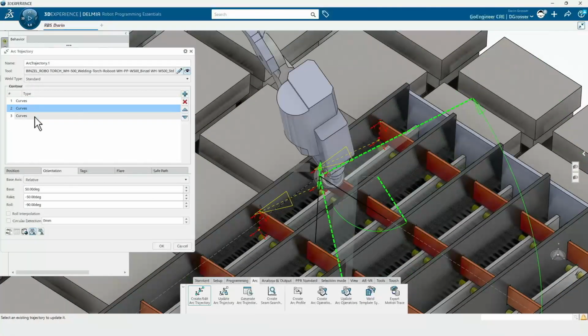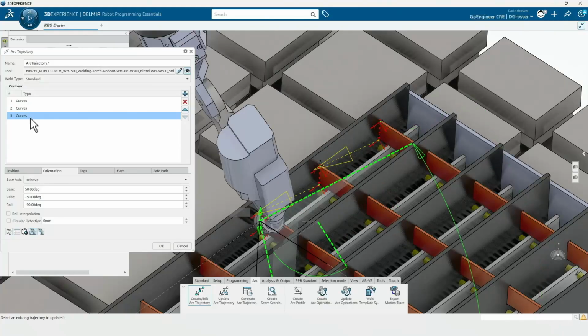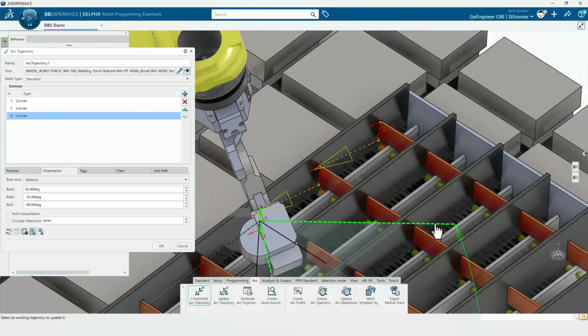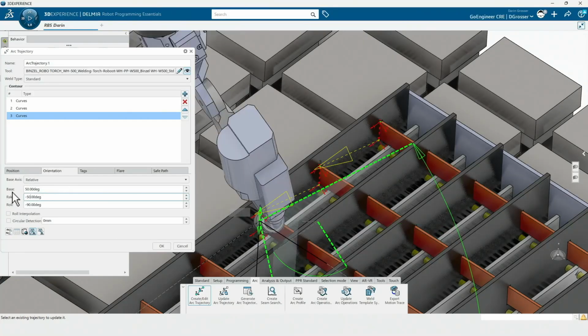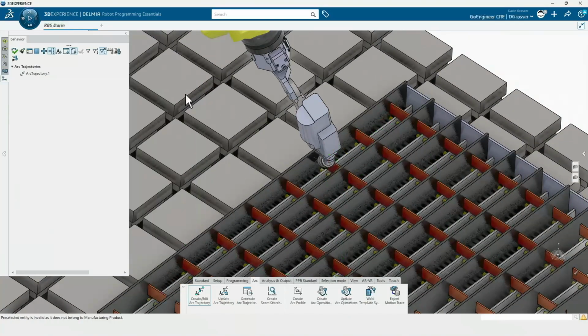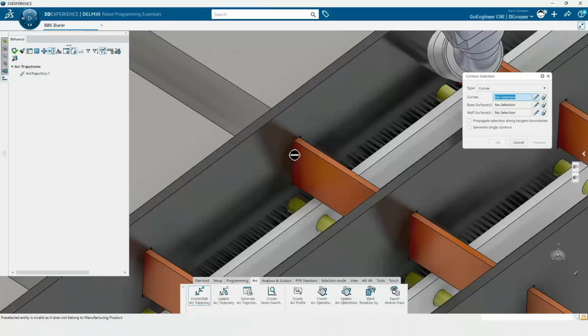Now, teaching also can include pulling that robot out to a specific spot in any way that you want, and then defining that as a point. And what that's going to do is put that into the overall tool path as it processes. And sometimes those are pull away and move points instead of the approach points or clearance points. So we just go ahead and set this up a little bit, and again, just ready to rock.